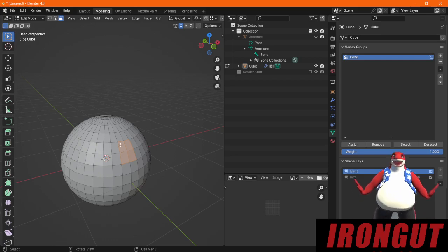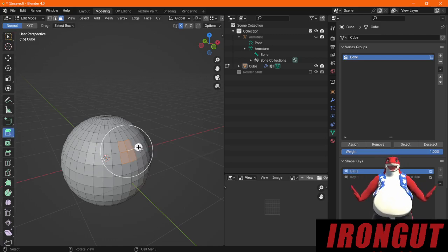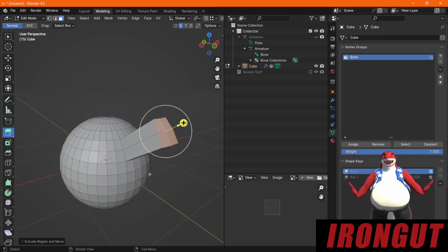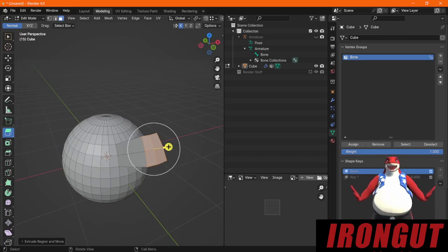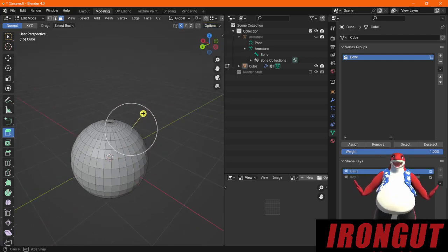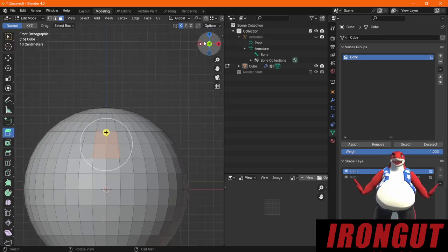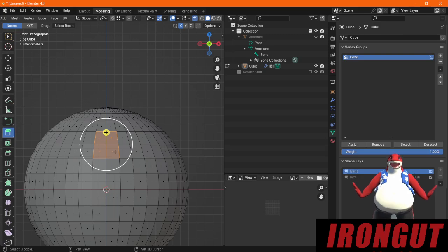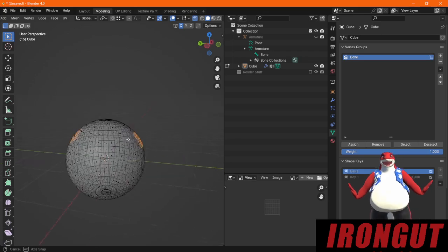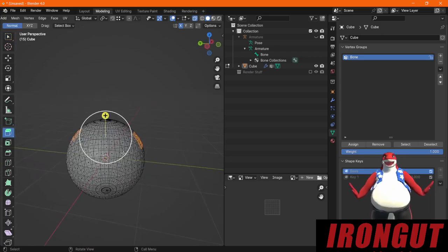But either way, the four arm polygons I think I've got good. So let's do, and this is going to be a really ugly arm. It's not going to be round at all. Okay, hang on. Well, that's okay. We can do this like this. Highlighting them on the other side. So now we have both sides highlighted. And then we use the extrude tool.